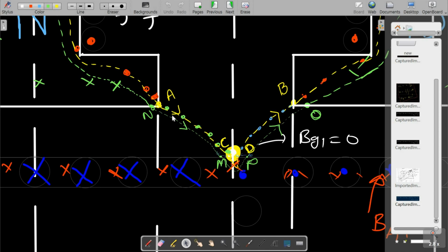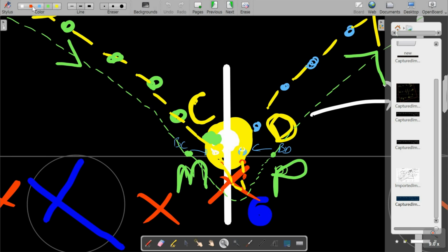Now I will say the flux density at this point M is Bm, and the flux density at P is Bp. These are just in the air gap, just above the surface of the armature iron. Now we will apply B equals mu H here, because the value of H is Hg2 at both, and the value of B is Bm and Bp respectively.